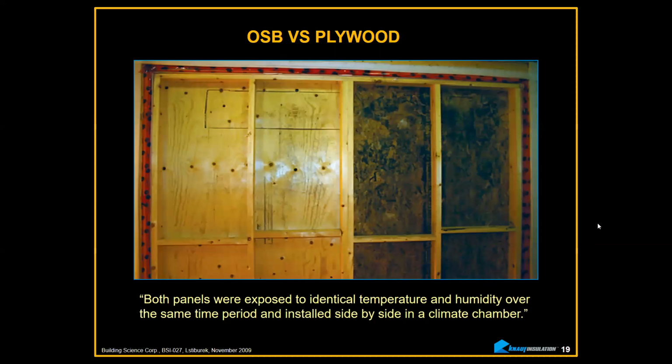So even if it's sloped correctly, you've got a wider gap against the wall instead of where that horizontal piece of the flashing, that pitched part of the flashing, covers the window trim. On the back side of that, there's an open hole. So it either has to be filled with a sealant or it has to be turned down on the edges. Most people don't do that. And again, when you get wind-driven rain, you're going to be in trouble because it's going to get right behind everything you don't want it to get behind.